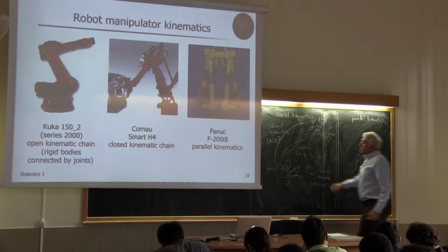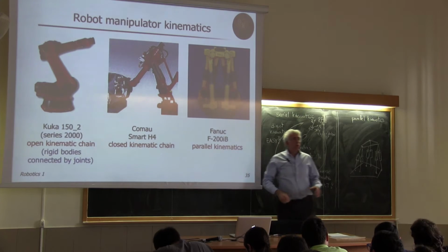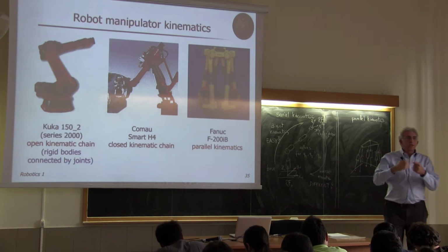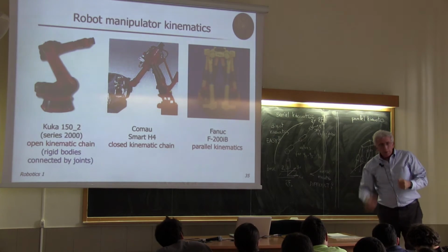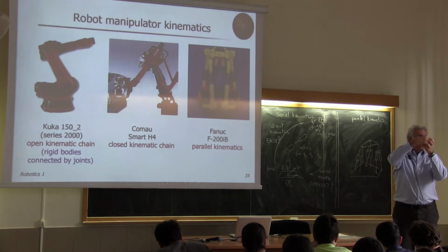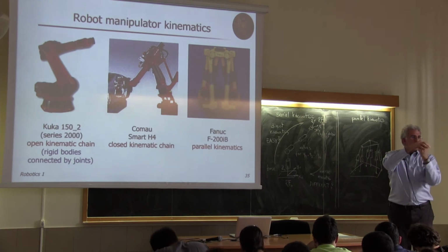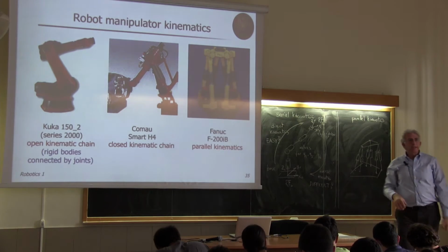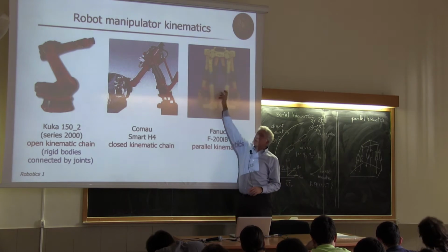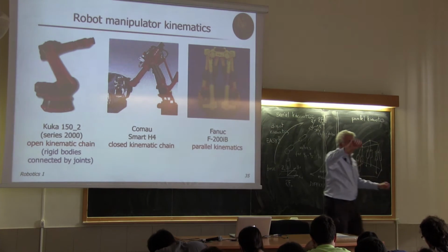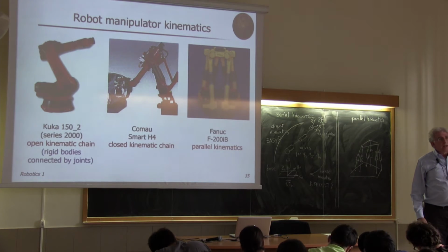You may wonder, what kind of joints do we have here at the base and at the top? These are called passive universal joints. It's like having a ball moving inside another ball and having the possibility of assuming any orientation, pointing, and so on. So these are passive, completely passive. There is no actuation. The only actuation extends or retracts the legs of this Stewart platform.